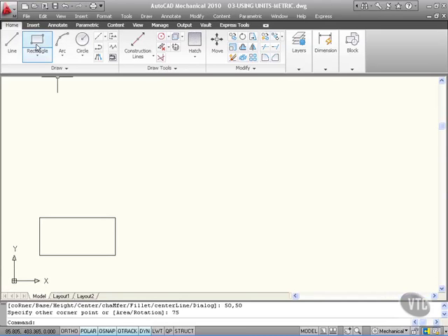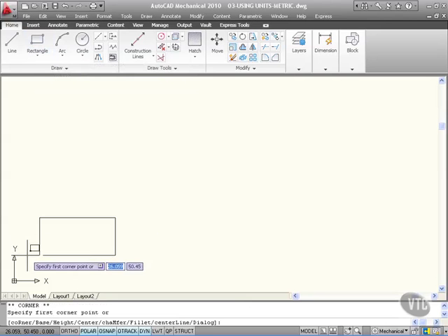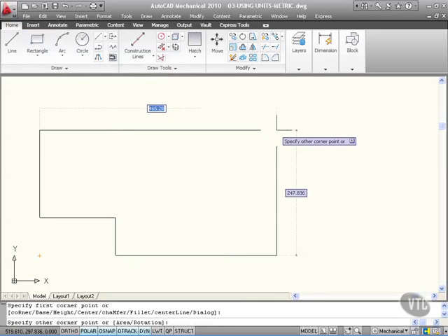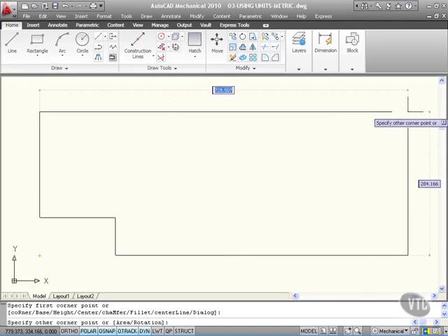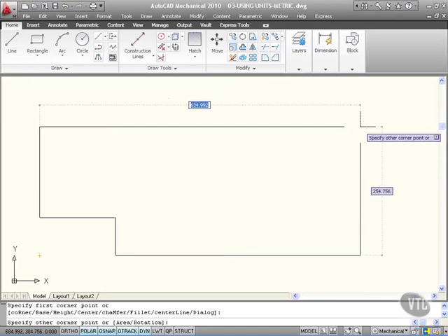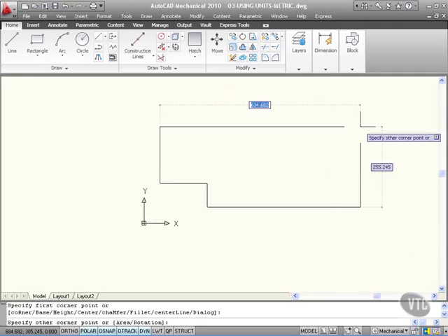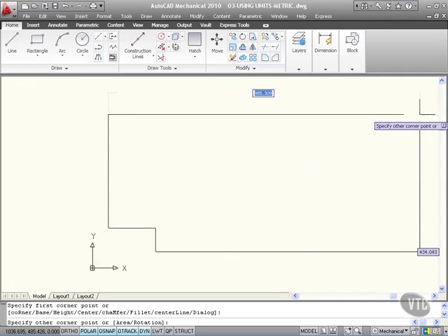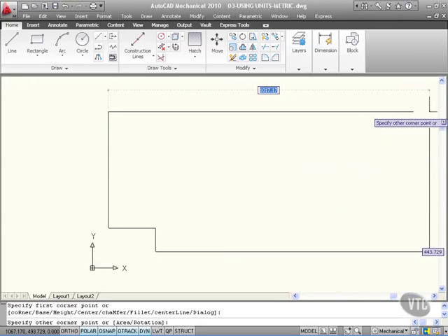I'm going to go to the rectangle command again, just click on the default rectangle there. And like with the imperial units exercise, I'm going to hover over that endpoint snap and left click. And as I drag outwards now, look, it just gets bigger and bigger and bigger. I'll zoom back a little bit on the wheel mouse to make that even smaller and pan again. And as I get bigger and bigger, look, as soon as I hit 1,000, it just goes to 1,000 millimeters. There's no distinction between a meter and a millimeter.